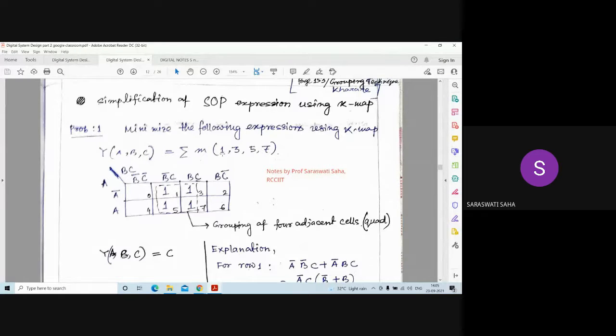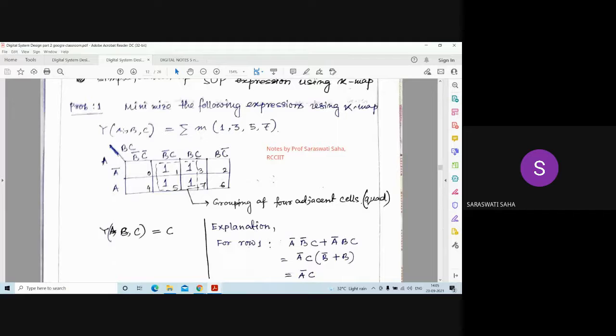So here it is clear from this expression that the output is a function of three input variables A, B, C. Now, as it is a function of three variables, first thing is to draw the Karnaugh map and represent it in this form. Why in this form? It is for 0, 0. It is for 0, 1. It is 1, 1. This is for 1, 0. And here it is for 0 and it is for 1. Is it clear in this form?